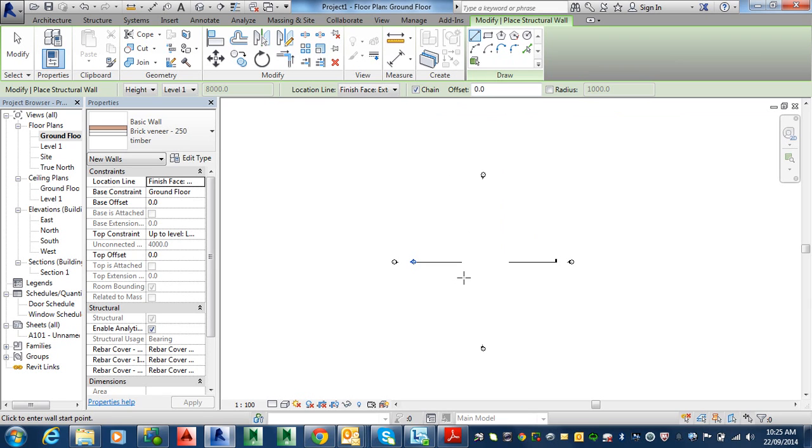So if I just try and draw somewhere in here, now these little symbols here are my little elevation symbols, which correspond to where it's looking at the house. If I click on the south elevation or whatever, it'll see the house. If I draw my house over here, those symbols are not looking at my house, so I won't see anything when I go to my east-west elevation or whatever. So you're going to draw it in here.